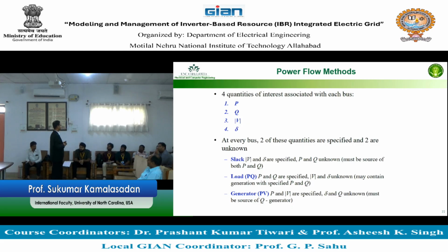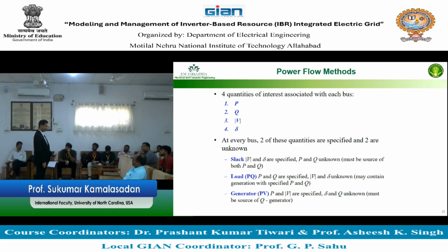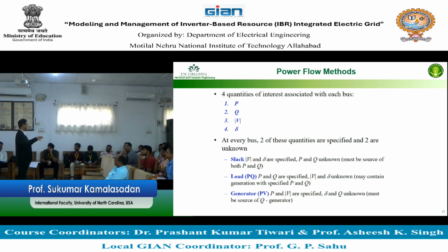Load frequency control is not done at a generator. Load frequency is controlled at the system level. But to get to load frequency control, somebody is doing control on the generator. Who is keeping the frequency at 60 hertz, so that the generator runs at synchronous speed? The second controller in a generator is called the governor. The governor is the one that governs or controls to keep the speed of the generator constant when the speed changes.